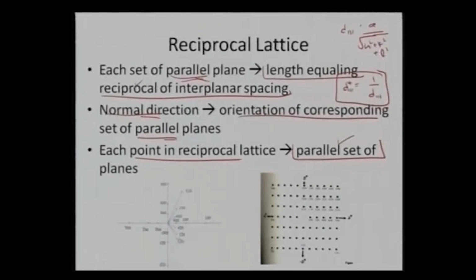So what I was seeing here, my 100 was here in the normal nomenclature, with 200 out here, 400 out here. But in terms of the reciprocal lattice, my 100 is out here, my 200 is double the spacing, my 400 is 4 times the spacing of 100. Now I can see all this part; I am basically opening it up to go to the other side, and I can see my lattice much more clearly.